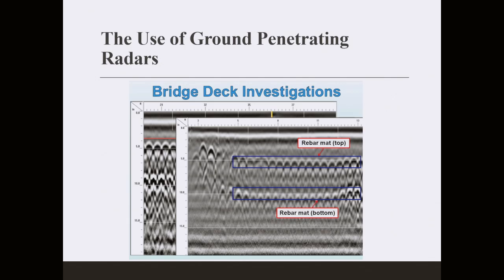Now, this one here shows us the outcome of a ground penetrating radar. It looks like a sonogram or a cardiograph. You need a medical doctor to read your cardiograph per se. This one you get like a one-week training in the company that produced the GPRs, and it can tell you how to correlate or how to read this. So you can spot if you have denser material or a thicker layer, like if you have soil layers, the thickness of every layer, what is the primary composition of every layer.